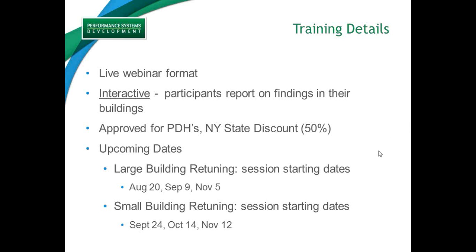Not in the kind of detail you might do for an ASHRAE audit, but to verify that you understand, I'm looking at air handling units 1 through 4, and I know exactly, according to the drawings, they are delivering air to these floors or these zones, and I walk through to verify, yep, I know what's going on on those floors, so that when I see wacky data trends, I either know that's a problem or no, that's actually the schedule on that floor. They leave for 4 hours in the middle of the day, something like that. So the walkthrough is important.